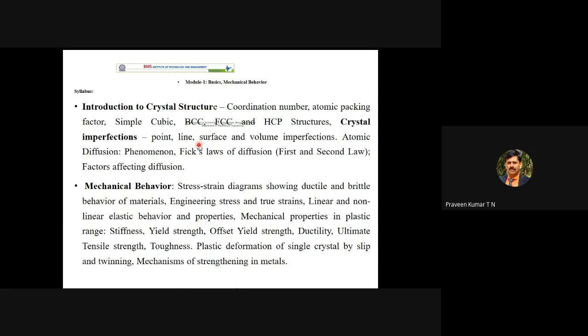So you are not discussing the surface, or what defects are present in the outer surface of the metal. You are discussing defects on the grain boundary or the surface of the grain. Those are defects known as surface defects. So don't think that surface defect means a defect in the outermost surface that is visible. No, it is not like that.